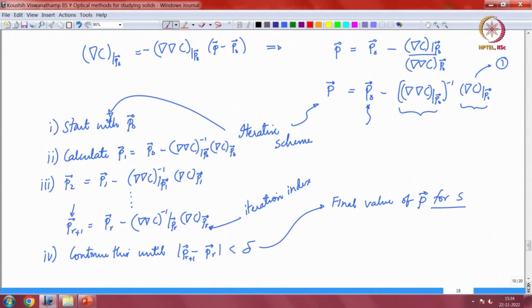In the last session we left off with an outline of the iterative scheme for determining the 6 component displacement vector with its gradients at each location. So, today we will look at a practical implementation of how to set up a simple DIC scheme. Like I said, there are many variants of DIC schemes that depend on some of the details that you choose to put in, how you choose to interpolate, how you choose to represent the grid, things like that. We will just see a bare bones implementation, so that if you are interested in pursuing some of these more detailed topics at a later stage, you can do that with this as a good basis.